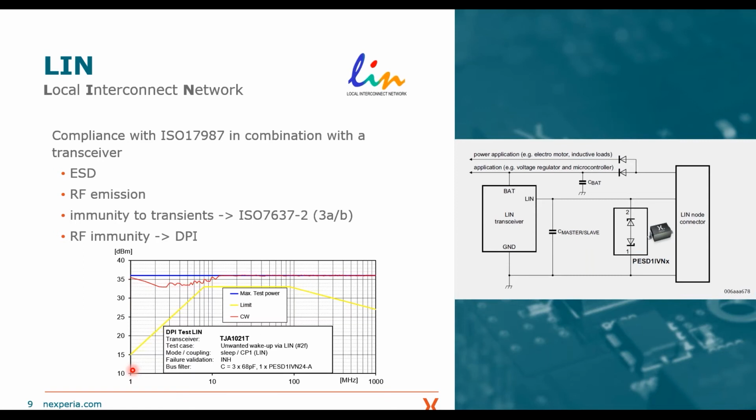As we said, it's usually not a problem, and from time to time, if there is a problem, the key solution is to change your ESD protection in order to have a higher clamping or trigger voltage. Because there are some high voltage transients within this test, and if you increase your triggering voltage, you avoid clamping of your device.